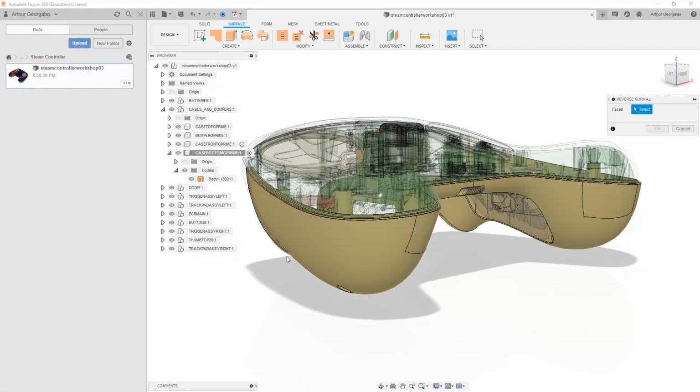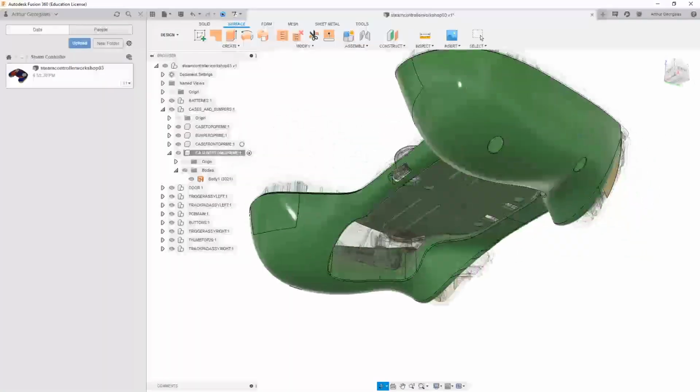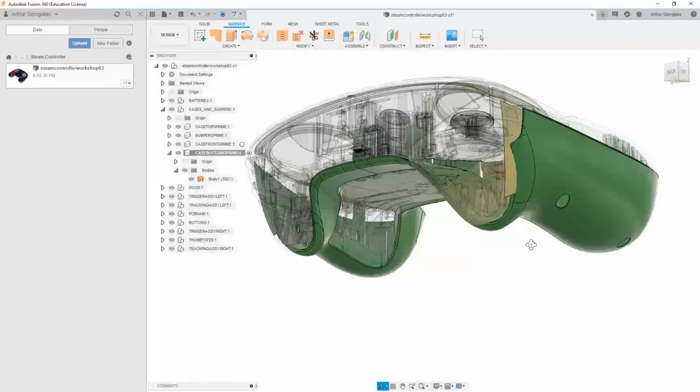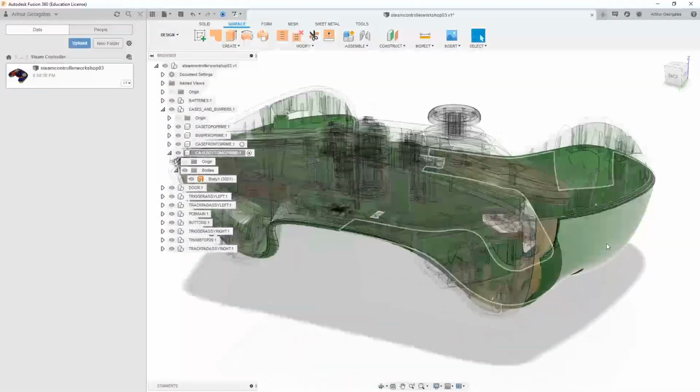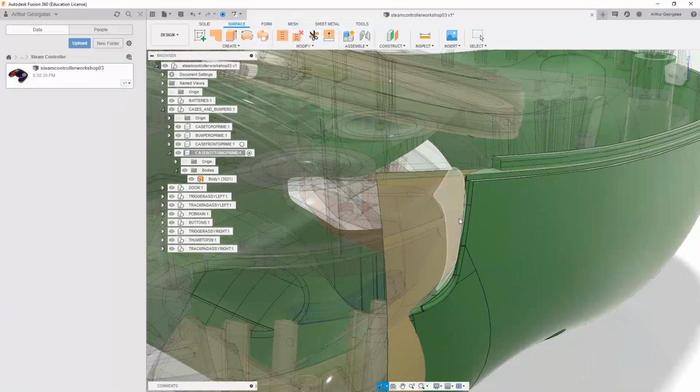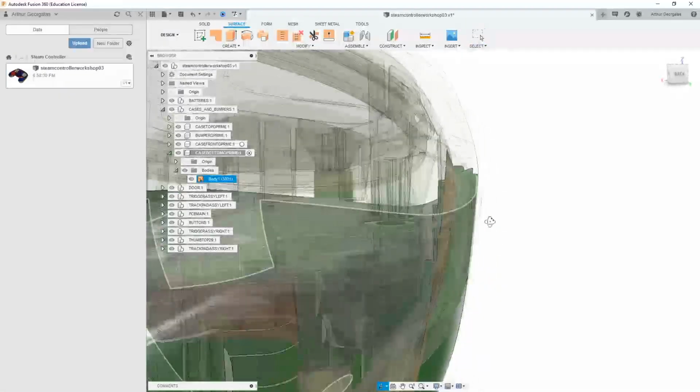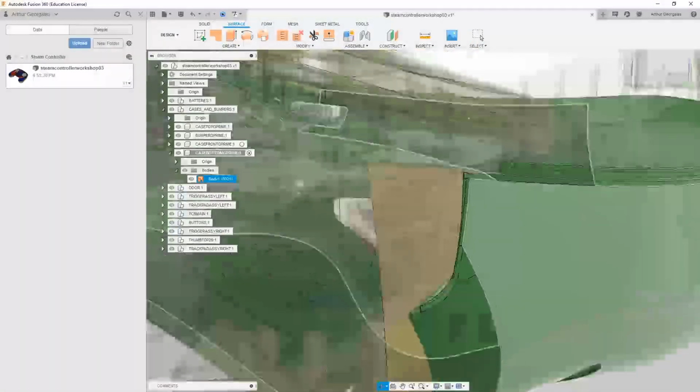So when I say A and B side, the A side is the normal side and the B side's the back side. It's just used sometimes for calculating appearances, saving processing power. It doesn't want to render things on the B side. So when we click that surface, it's all one big face. We go OK, and now it's flipped the right way out, and our appearance is working properly.